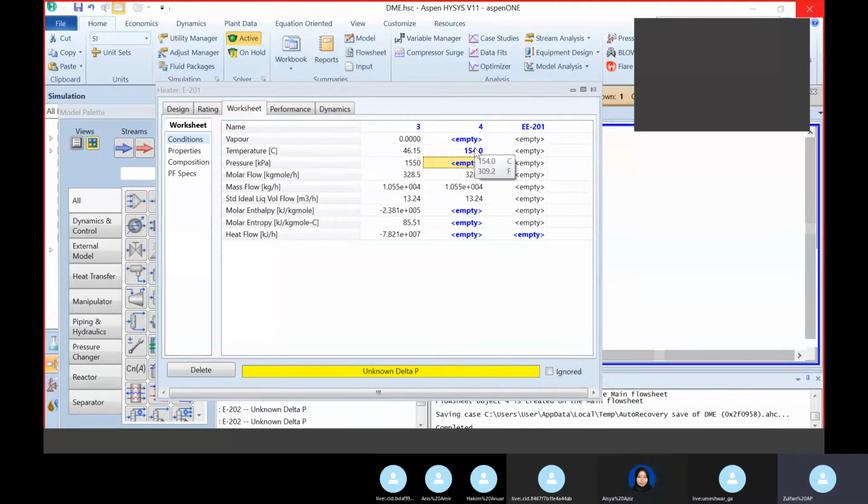Okay. So that QMCp delta T is done, but then it still requires us to know the pressure outlet. That is typical because it is related to the flash calculation in the heater. We need to have pressure and temperature calculated, so that it will know the condition, the phase of the stream.